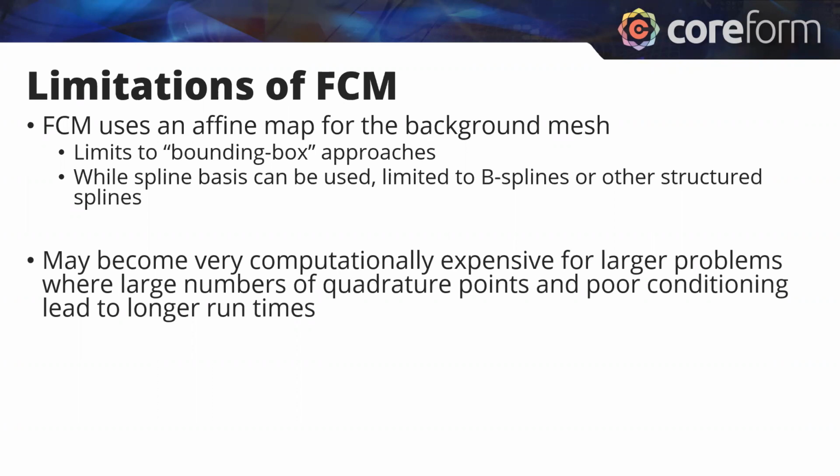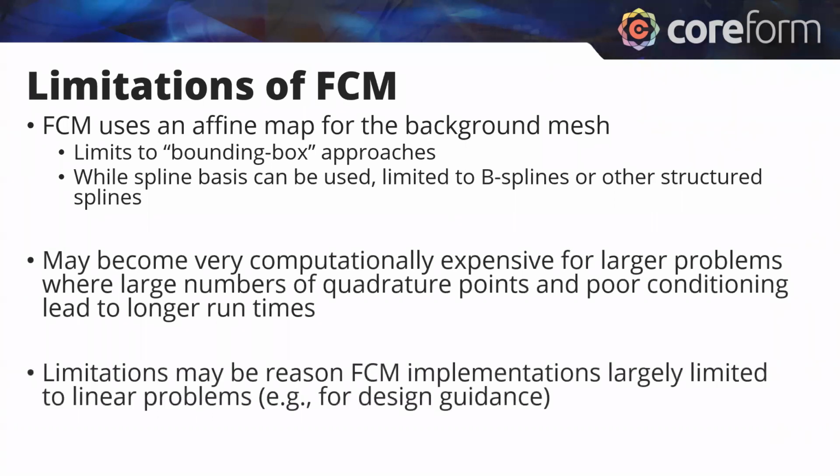And maybe for a variety of different reasons, they tend to be very computationally expensive because of that bounding box approach, and maybe put a little bit more effort on the computers, and maybe just can't solve certain kinds of problems. So it's at least appeared that from a commercial implementation standpoint, most implementations of the finite cell method do seem to be limited to linear or small nonlinear, like barely nonlinear problems, and mostly seem to be for design guidance sorts of analyses.